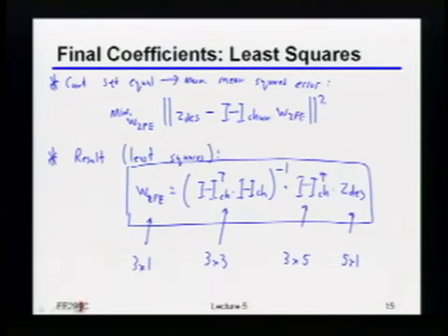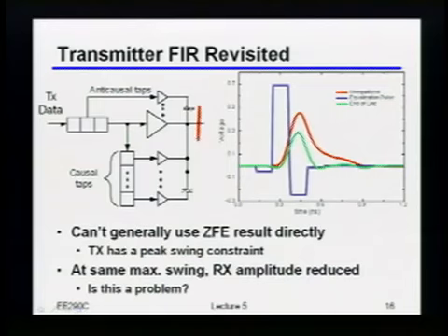As you can probably imagine, there's a maximum signal swing that you'd like to put out of your transmitter. So you have to make sure that the maximum signal you transmit, including all of the equalization, is still fixed, and then you can only scale things underneath that. In particular, if you look at this black waveform, that was my transmitted pre-emphasized waveform.